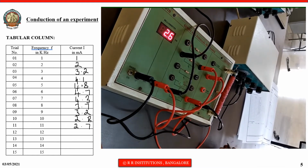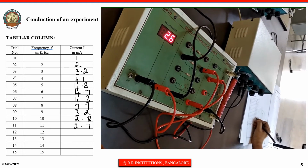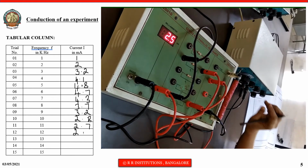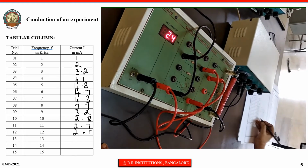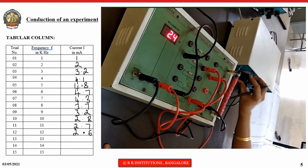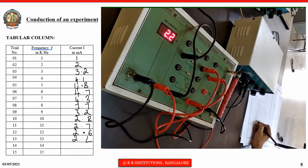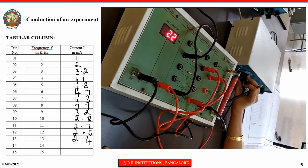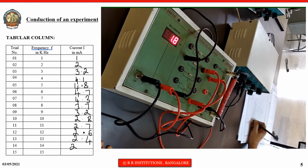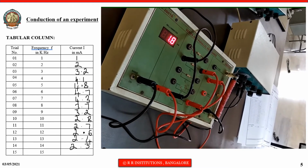For 12 it is 2.6. For 13 kilohertz it is 2.4. For 14 kilohertz it is 2.3. For 15 kilohertz it is 1.9. So this is how we must record the frequency response.